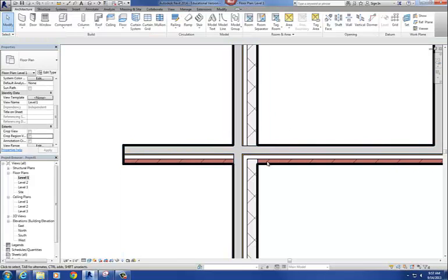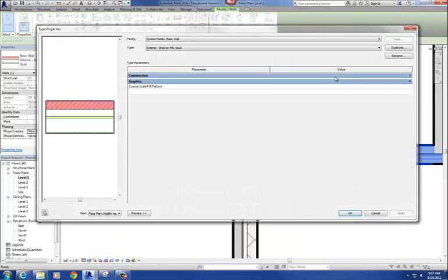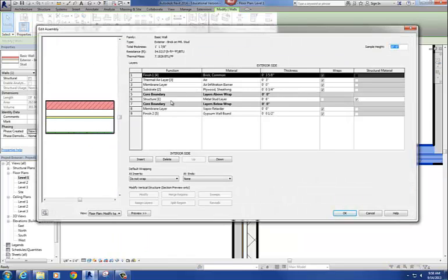All right. So basically, when the brick stops at a certain wall, that has to do with those functional priorities here. Like I said, the lower the number here, the higher the priority. So the metal stud layer is the highest priority. That means it'll cut through any material that has a lower priority. So on that opposite wall that it's cutting through, it'll cut through the priority 5 wall material, and the priority 2 material, and the priority 3 material.